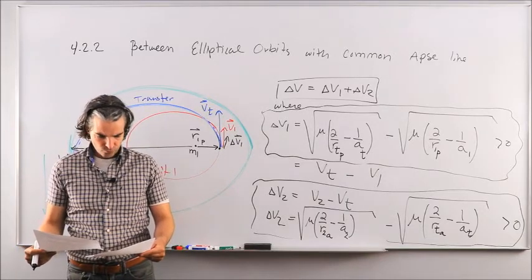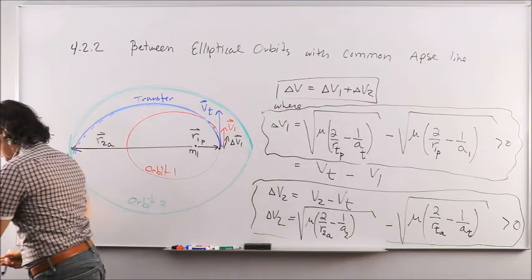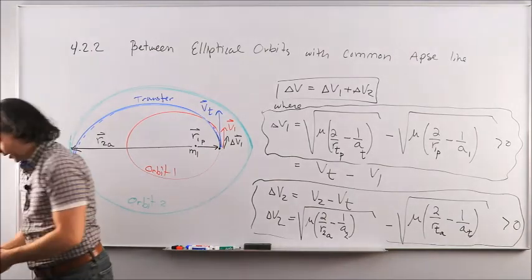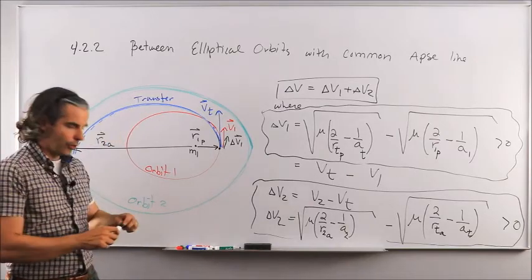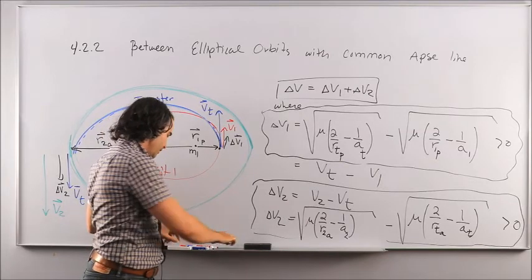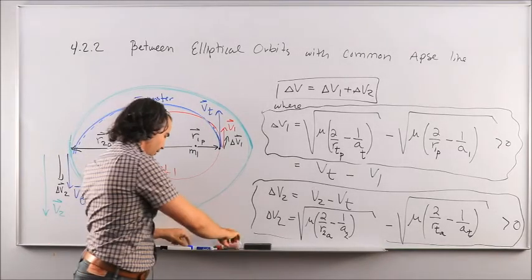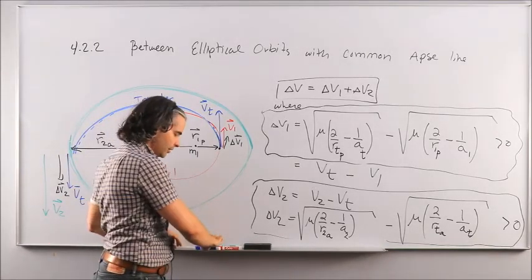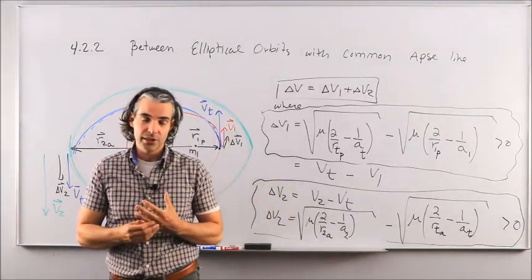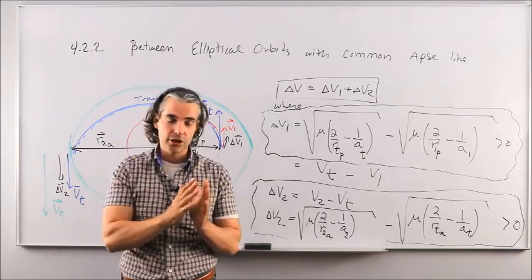I think I'm going to end here for this lecture, because that seems like a good point to stop. So that kind of covers the very fundamentals of orbital maneuvers, and specifically for impulsive, coplanar, tangential maneuvers. So in the next lecture or so, we're going to look at more complex maneuvers that will allow us to not only stretch or compress the orbit in terms of semi-major axis and eccentricity, but also change the orbital plane in 3 dimensions, changing the node, changing inclination.